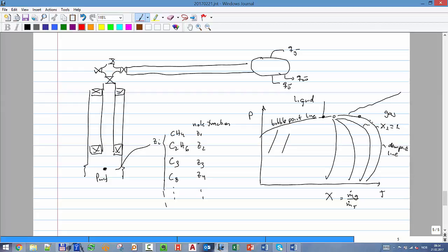Okay. Now let's assume that that point is someplace here, inside, that I'm entering already in a mixture. Let's put it on that side. We are saying it's an oil. Okay, so we have that point. And when I'm evolving in the tubing along the system, I will be losing pressure and losing temperature, right? The fluid will be cooled, and also the pressure will reduce. So the line will be something like that. At this point I have certain mixture, okay? And then when I'm progressing along the tubing, I'm increasing the amount of gas gradually. So let's say here, initially we can say, for example, that we have just a few bubbles of liquid.